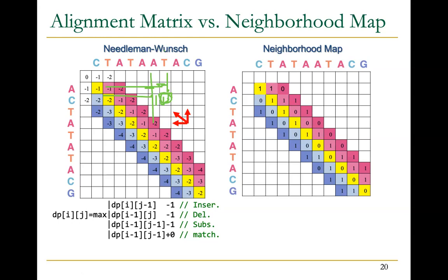So you can do it in one operation in the FPGA, for example, or one SIMD register, you can load everything over there if it fits in 256 or in 512, depending on what kind of SIMD lane you are using. If it fits, then you can do it in one cycle, right? Because everything is independent, and you can do it for all vectors together in parallel. So you can do shifting to the right, shifting to the left, shifting by 2 steps to the right, and so on. All of these are still independent.